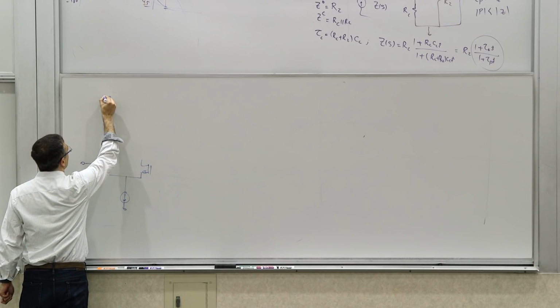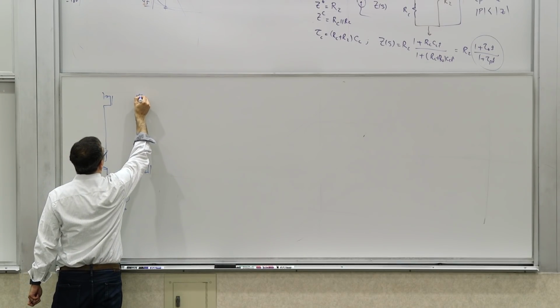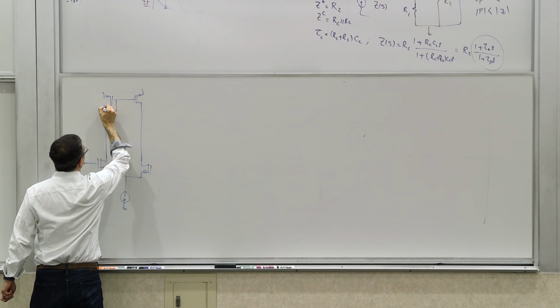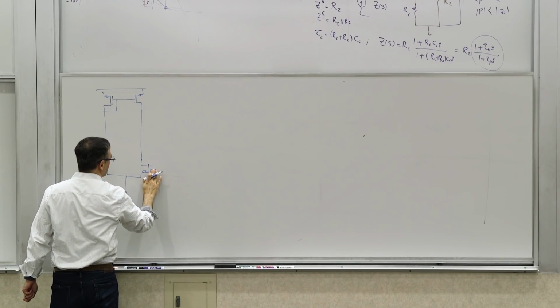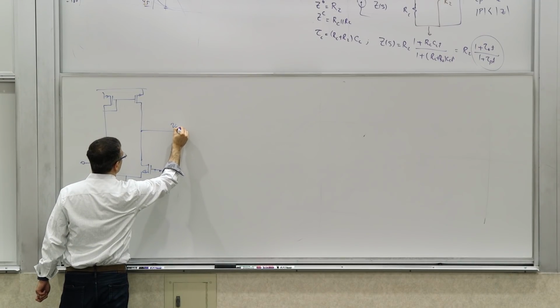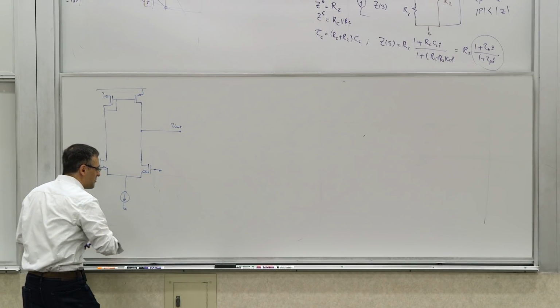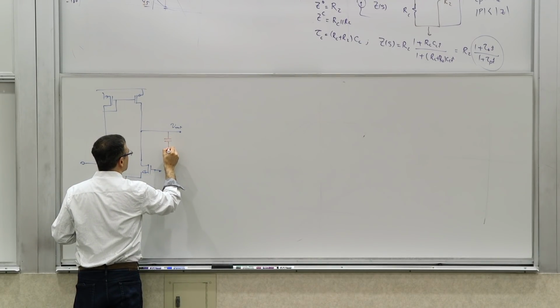Let's use MOSFETs. And then you had a current mirror off the top. So it converts the differential input to a single-ended output, Vout. And then you can imagine that you will have some sort of capacitive load that can be dominating, CL.